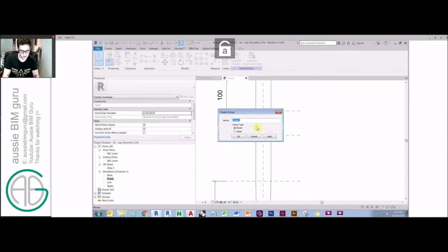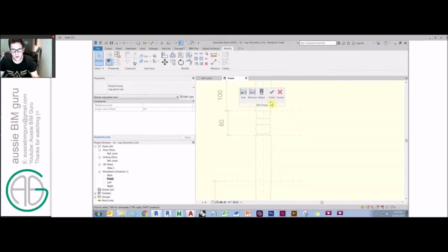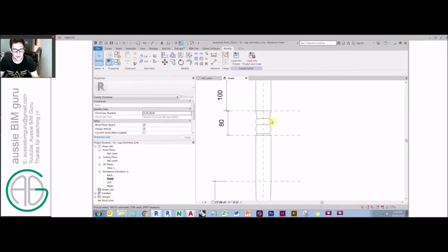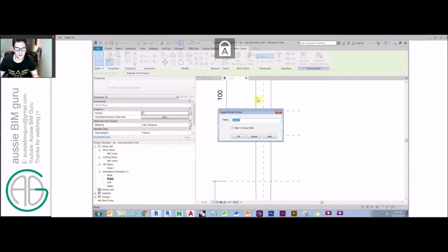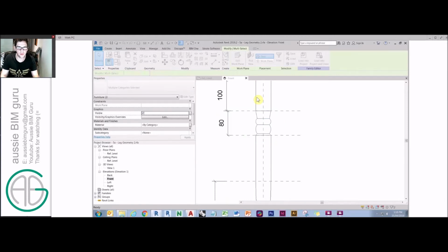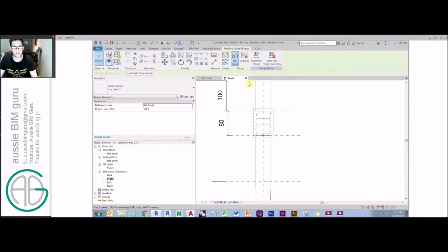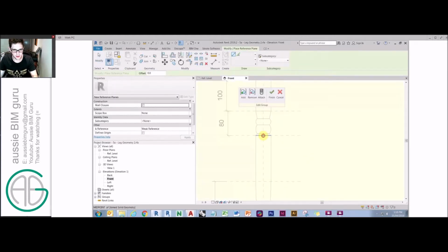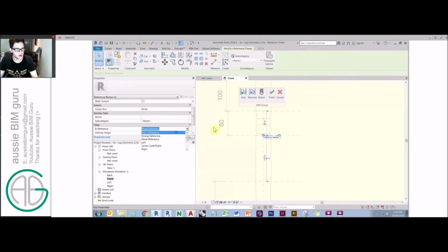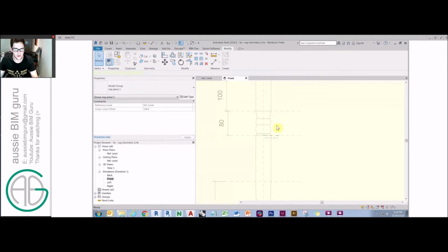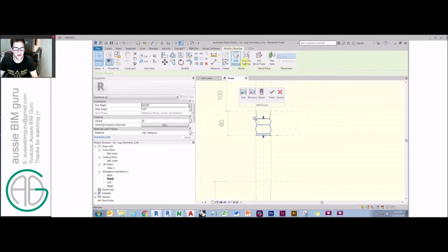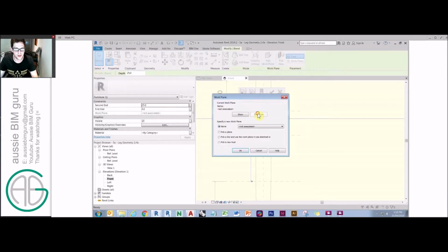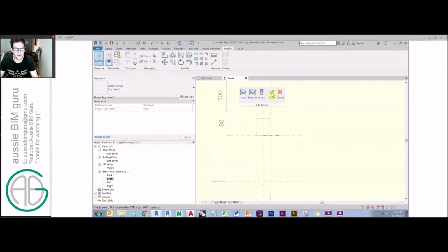And we'll just call this leg piece 1 group. Great. Okay. And then from there, inside that group, we'll add a reference plane that we can use to constrain the group instead. And we'll disassociate these elements from a work plane, just so they're free and don't get driven by any reference planes anymore.